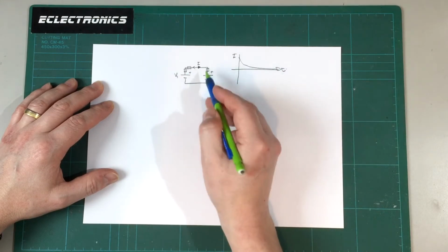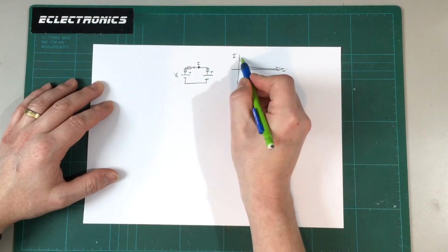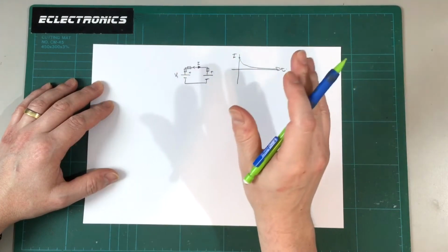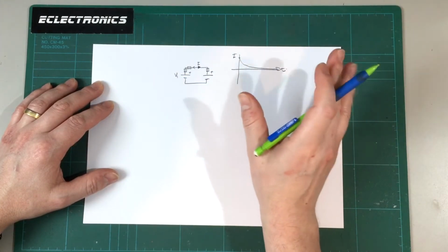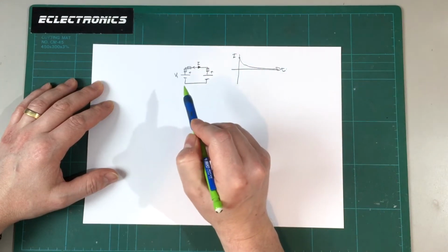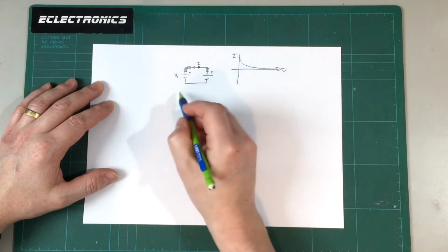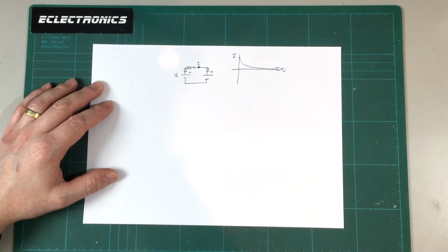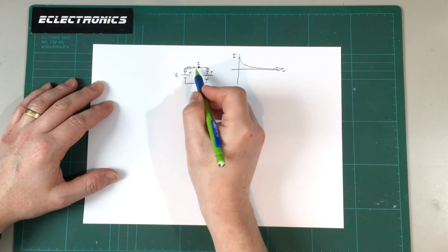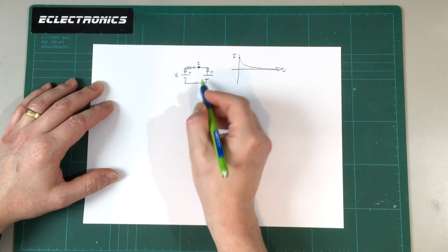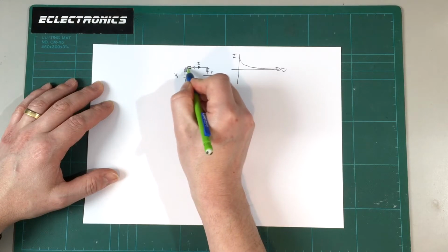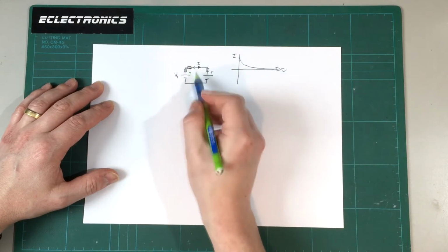So we've got these three elements which determine what our peak current's going to be when we just connect cells together like this, which by the way you should probably never do unless you know those cells are pretty balanced to start with. You could get some pretty high currents flowing, so it's not advisable to do that. So what will the characteristic be here for this kind of simple charge balancing circuit, which let's say we had an external resistor which we were putting between the cells to make it more safe? What would the characteristic of that balancing circuit look like?